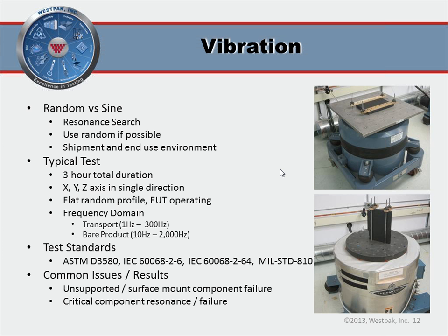When we do vibration testing, we want to make sure that the test inputs clearly help us define what we're looking for. Vibration itself is not a harmful input most of the time. Vibration levels, even on transportation vehicles, which are going to be pretty severe on occasion, rarely exceed a half a G RMS, and most products will have fragility levels well above that. It's only when we excite resonances within the product or the package or both that we are concerned. So vibration testing is really what I refer to as a hunt for resonance. That's the big deal. That's the killer.